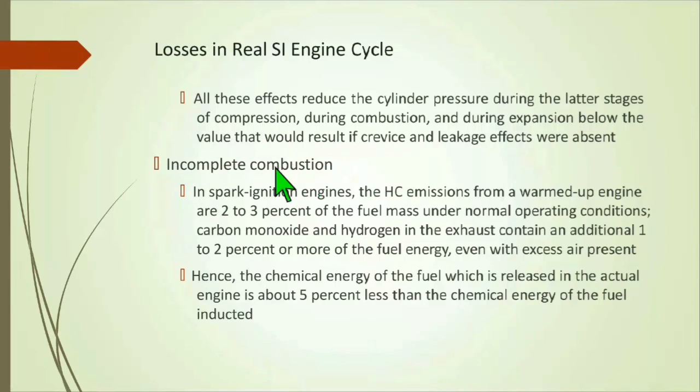Incomplete combustion. In spark ignition engines, the hydrocarbon emissions from a warmed-up engine are 2 to 3% of the fuel mass under normal operating conditions. Carbon monoxide and hydrogen in the exhaust contain an additional 1 to 2% or more of the fuel energy, even with excess air present. Hence, the chemical energy of the fuel which is released in the actual engine is about 5% less than the chemical energy of the fuel injected.